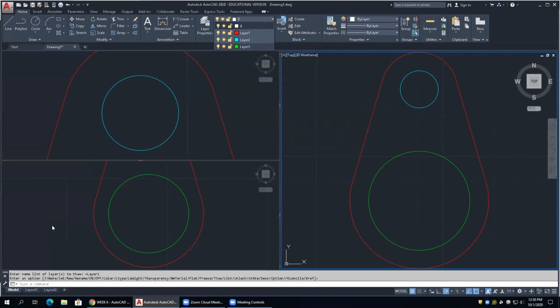So what happened though is, it's kind of driven that way now. And so now basically what it's for is for you to be able to plot from paper space. You can still see your model, but you can plot everything 1-to-1. And the way we handle scale factors, we'll handle the scale factors in the viewports themselves. We're still drawing our model full scale, but we're going to handle it through the viewports.